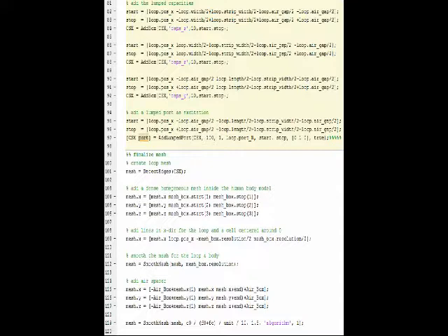Therefore we need the detect edges function here, and we override the mesh parameter. To add a dense homogeneous mesh, we create it in the x, y, z direction, and then we add lines in the x direction for the loop and the cell centered around 0. Only in the x direction, we take the mesh box resolution parameter. We set it to 2, and then we use it here.